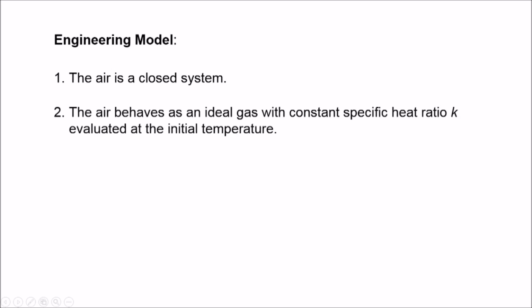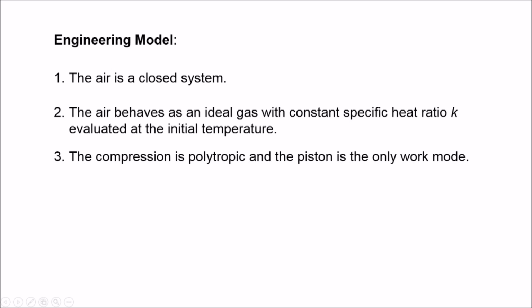The next step is to develop an engineering model, which is a set of simplifying assumptions which will allow us to perform the analysis of the problem. 1. The air is a closed system. 2. The air behaves as an ideal gas with constant specific heat ratio k evaluated at the initial temperature. 3. The compression is polytropic and the piston is the only work mode. And 4. There is no change in kinetic or potential energy.